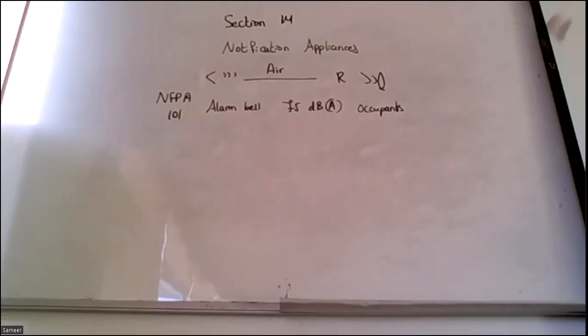Then we have the C weighting scale. The C weighting scale is a scale of impact: sudden explosion, sudden large noise that can damage the hearing of human ears. So that is dBC, impact noise, explosion noise.